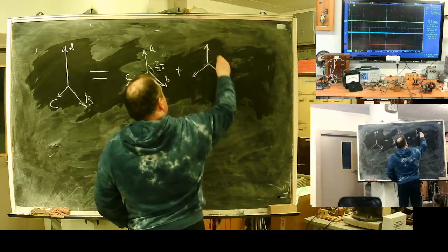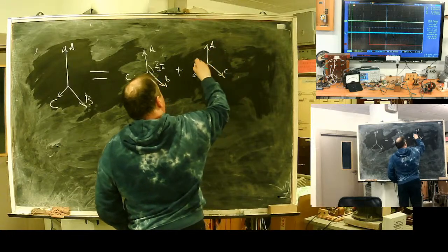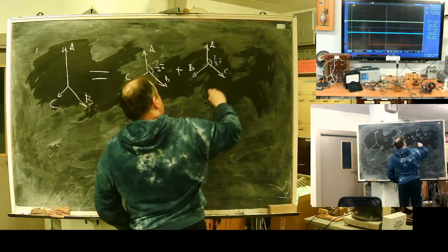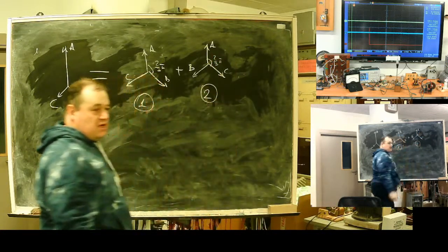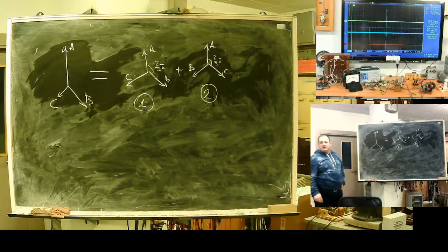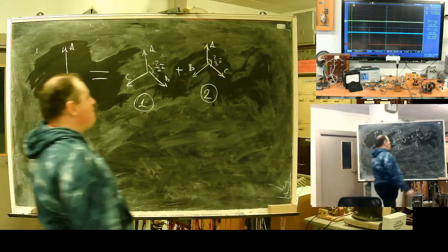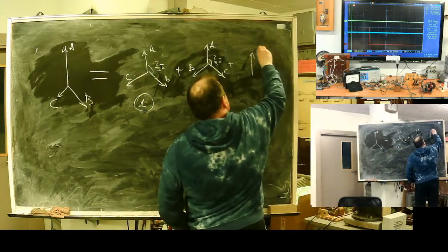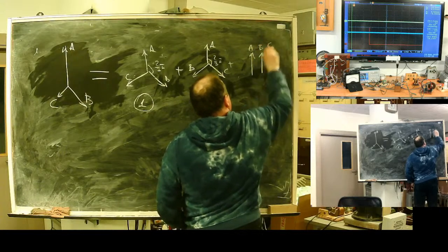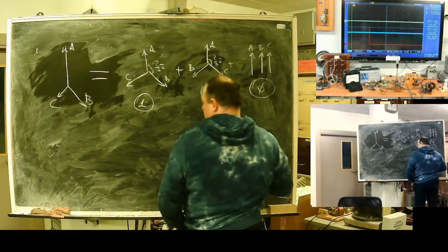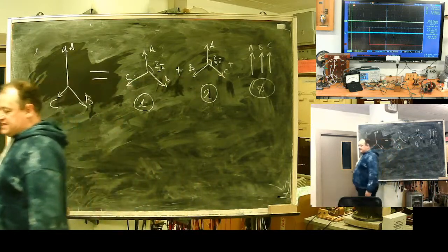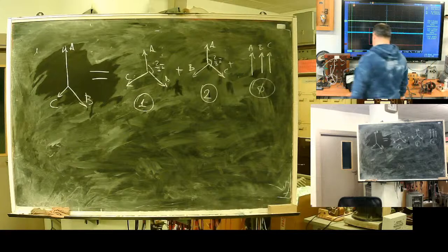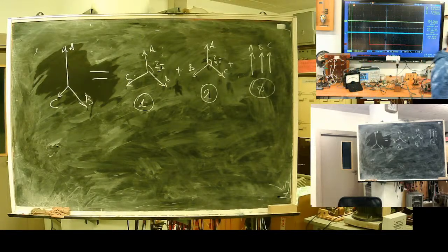It's ideal symmetric but has an opposite phase sequence. It's like an ideal generator but rotating in the opposite direction. Plus zero sequence system. It's not in Fortescue but Wagner and Evans marked it with a 0. Zero sequence system represents a ground or neutral current.